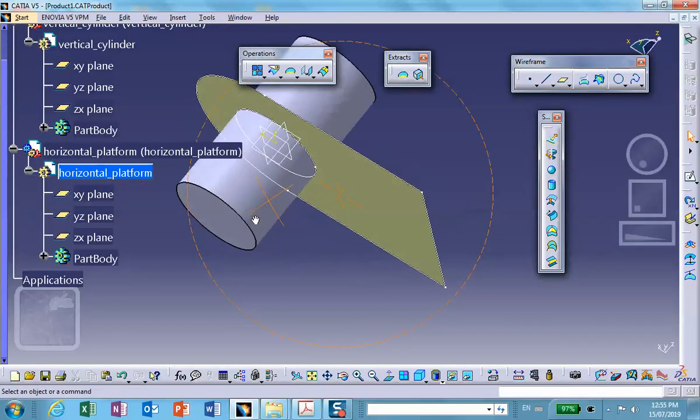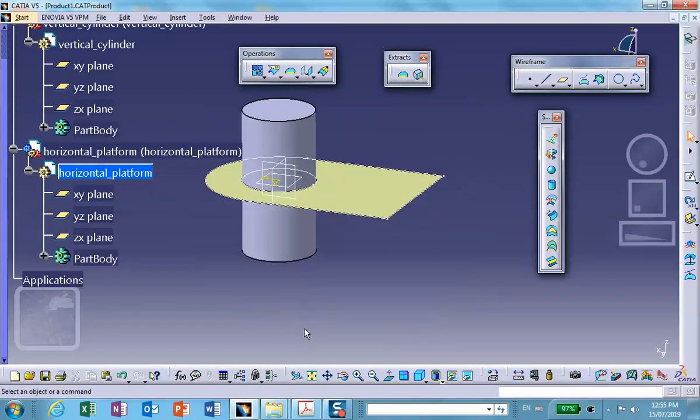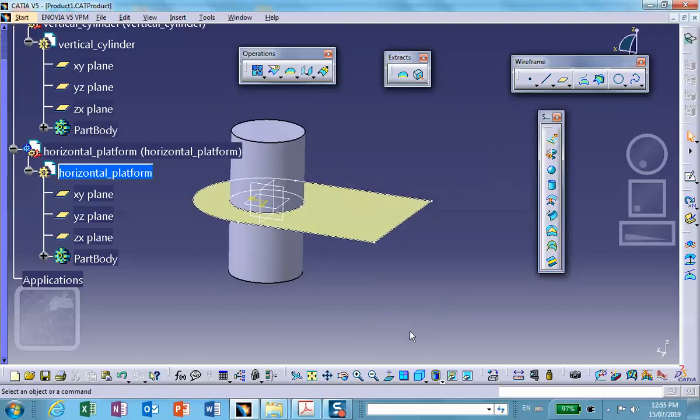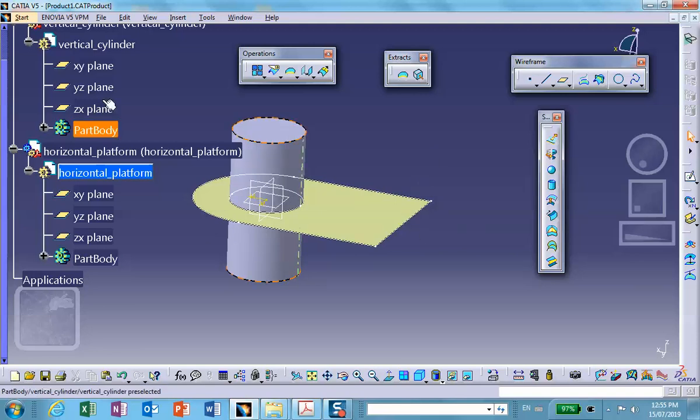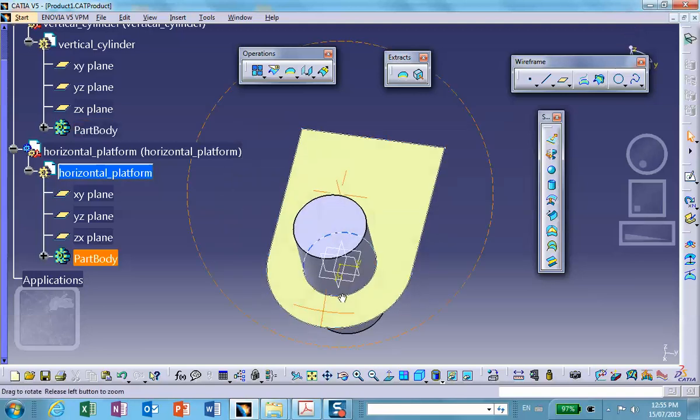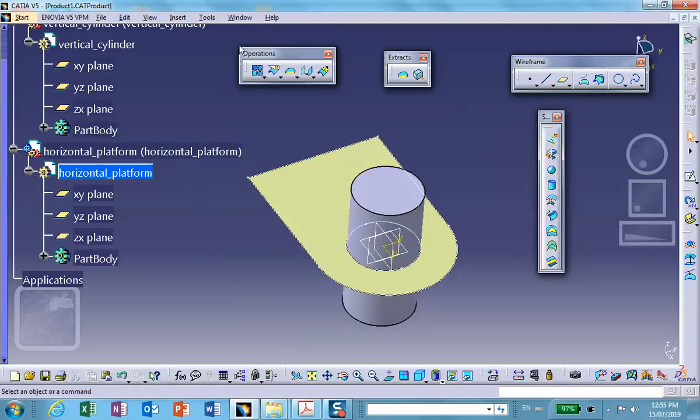Now in the book, as I said, I created a solid object, extracted the top face, and all kinds of crazy things that are not needed. Well, I mean, you get to learn these things, but it's not needed. All right, now, what we would like to do is insert the left column and the right column here as separate parts.